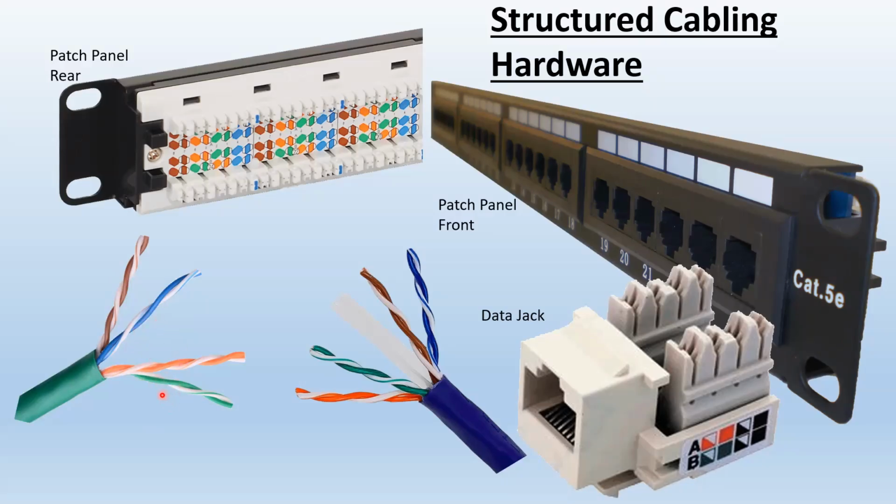This is just to eliminate the possibility of something that's called crosstalk. We'll talk about that later. Now, the twist eliminates crosstalk. Cat6, to eliminate more crosstalk, will have a tighter twist, more consistent twist within the pair, but also the twists are different, so they are not twisted at the same rate, so the crosstalk still is getting eliminated by that.